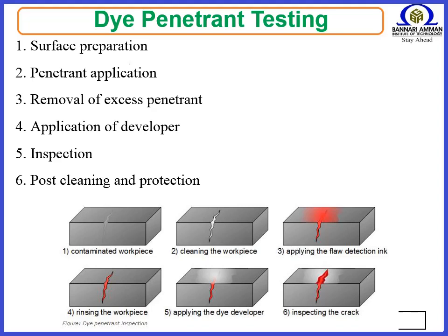When removing the penetrant, the operator must be careful not to remove any penetrant that has flowed into voids. A light coating of developer is then applied to the surface and given time, the developer dwell time, to allow the penetrant from any voids or fissures to seep up into the developer, creating a visible indication. Following the prescribed developer dwell time, the part is inspected visually, with the aid of a black light for fluorescent penetrants. Most developers are fine-grained, white talcum-like powders that provide a color contrast to the penetrant being used.